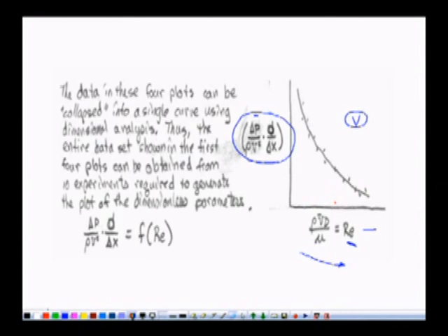If we want to know, at a given velocity, given density, given viscosity, given diameter, what is the corresponding del P over del X, right. So, substitute in this equation rho V d divided by mu, find out that number, the Reynolds number. So, let us say it is like this, and corresponding to this point, go in a perpendicular direction, locate this point, and corresponding to this point find out the corresponding value of del P over rho V square into d over delta x.